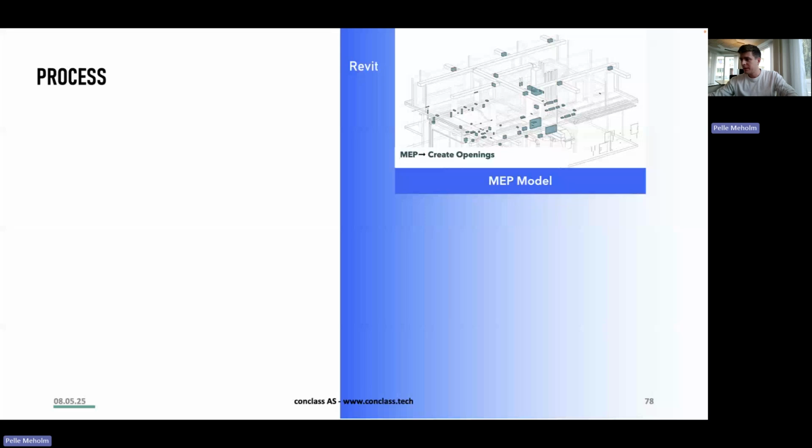Perfect. It will take some seconds. Perfect, thank you. Yeah, that was a short overview on how to create openings. As I said, we will not go into the details. If you have questions, we're going to answer them afterwards. But you can run the process for your entire project, creating openings for a huge part of your project. It allows you to create thousands of openings at once.